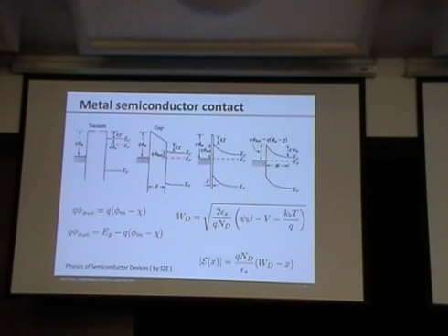The question we could ask is how much of our device in a working device looks like this depletion width or this depleted area, i.e. we have essentially band bending, non-flat bands due to the details of our contacts, versus how much looks like flat band and bulk. That depends on the thickness, because if the thickness is too small, we are not going to see any band bending. That is absolutely true. And how thick are these devices typically for these high-performance polymers?